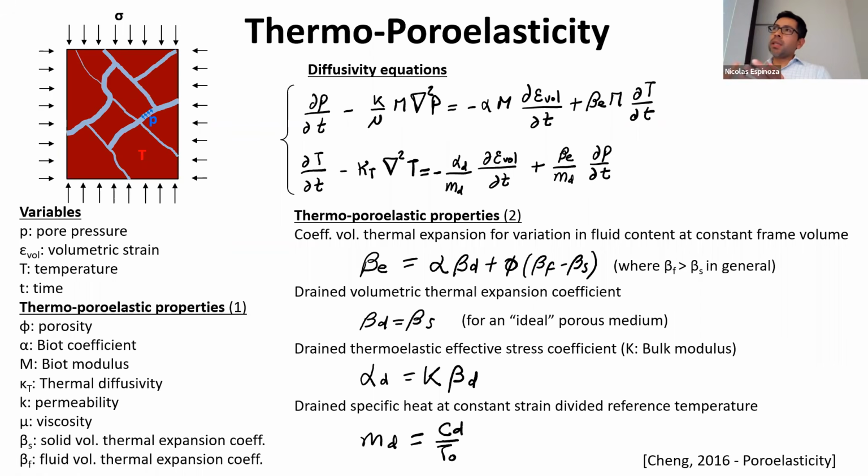What that means is that if you have a rock filled with water and you heat it up, and don't consider now the change of phase by going into, say, vapor. If you just heat it up, the fluid is going to expand more than the rock. And if the fluid expands more than the rock, and you don't let the fluid get out of the rock, either because you seal the rock around or because the permeability of your rock is very low, then you're going to generate internal pore pressure. And that internal pore pressure can also fracture your rock.